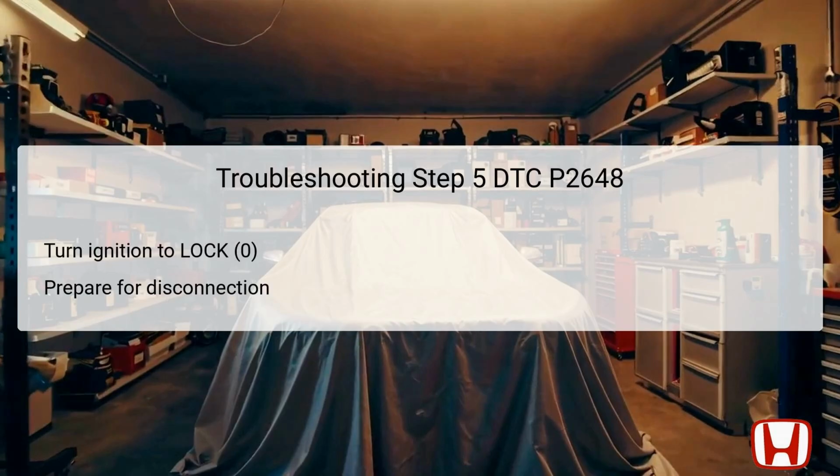For the fifth step, turn the ignition switch to the LOCK position to ensure that the vehicle systems are completely powered down before proceeding. This is crucial for safe handling and manipulation of electronic components without risking shorts or other electrical issues.